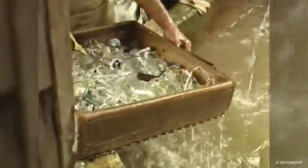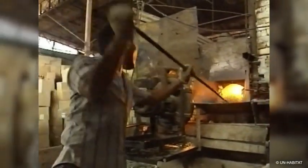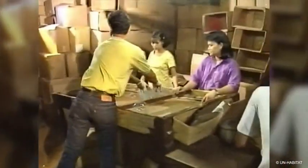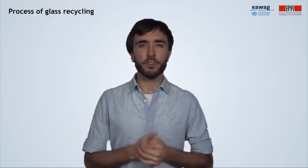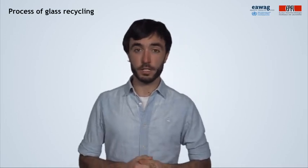First, the cullet is obtained from storage, and it is manually separated and washed. Then, this broken glass is introduced in the furnace to be remelted. The melted glass is used for production of new bottles, which are later sold again. Cullet has the advantage that it prolongs furnace life as it melts at lower temperatures. As long as contaminants are removed, there is no quality loss of glass in the recycling process. Once colored cullet is mixed, however, the quality degrades.